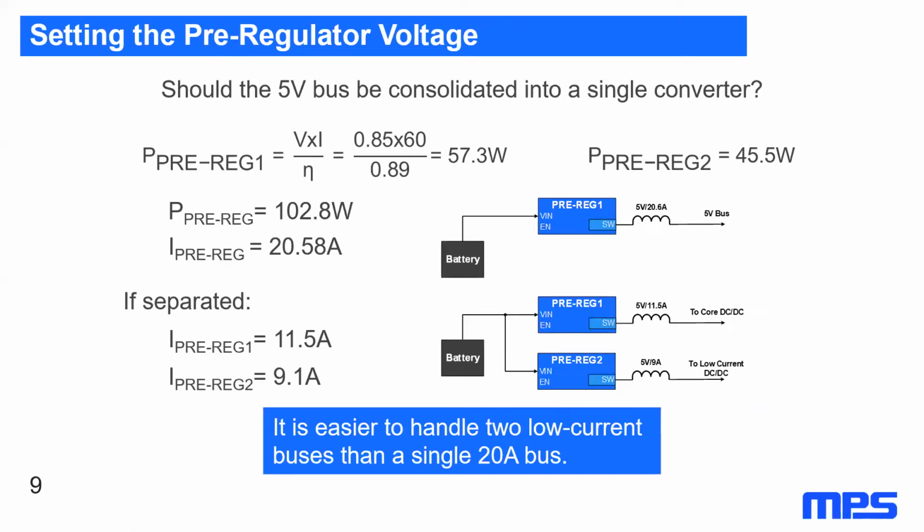So this tends to radiate a lot of EMI, electromagnetic interference. It is usually easier to contain the EMI of 2 smaller regulators and to spread the heat into 2 different regulators than to have everything on a single DC-DC converter. So in our case, we select to have 2 different pre-regulator stages to both spread the heat and contain the EMI.